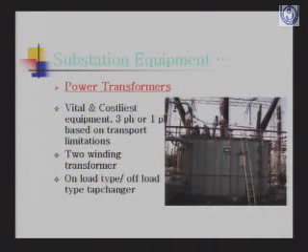So the power transformer. This is the most vital and costliest equipment of a substation. The power transformer can be 3-phase or single-phase based on transport limitations. It's generally a 2-winding transformer, and it has an on-load or an off-load tap changer for changing the voltage which is coming at the bus bar terminals. These tap changes are in the range of plus minus 2.5%.